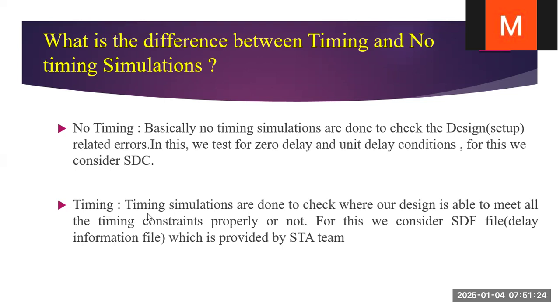Timing simulations are done to check whether our design is able to meet all the timing constraints properly or not. For this, we will consider the SDF, standard delay format file, which contains the delay information provided by the STA team, the static timing analysis team.